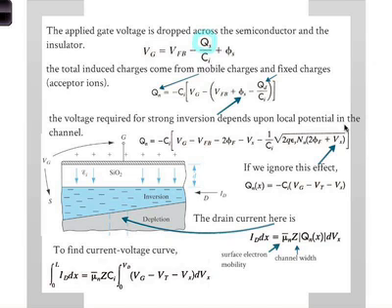That's another way to think about it. Depletion is one way to think about it because I think it's easier that way. But you can also think about inversion. Let's look at any random point in the channel. The reason holes will come to this point is that the potential here is more negative than the bulk, so the holes will come close. And the reason it's more negative is because you're applying a negative voltage here, because there's a drop and so on. But it is the local potential that gives you those holes.